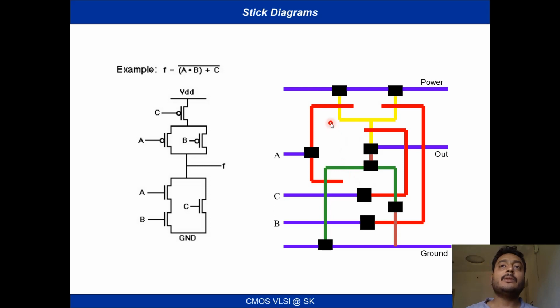So what we will do is go for a technique called Euler's method, where you write a Euler's graph for your circuit and identify the Euler's path for it. Then you are going to draw the stick diagram. Okay. So this is also a correct way. If in an examination somebody gives you this equation, you can write the stick diagram in this fashion also. No issues with it. Okay. They have to give you marks, but it's better if you depict the stick diagram in terms of Euler's method. Okay, so getting the Euler's path and then writing the stick diagram.